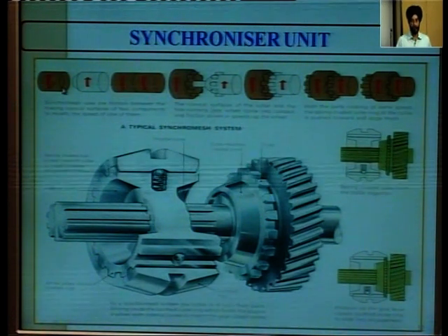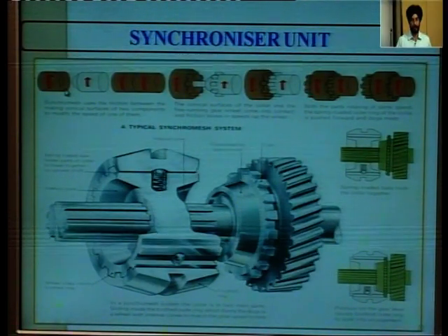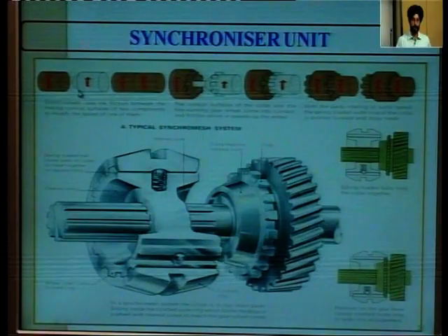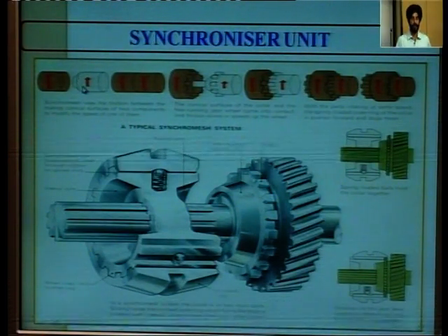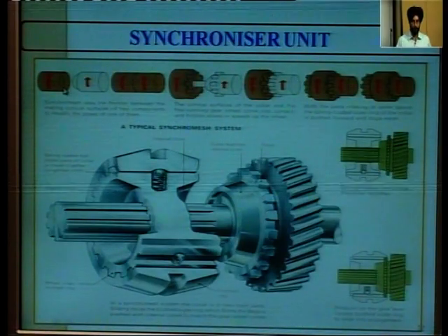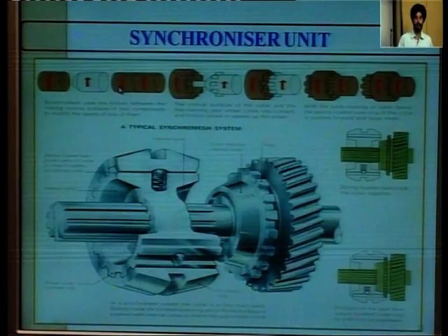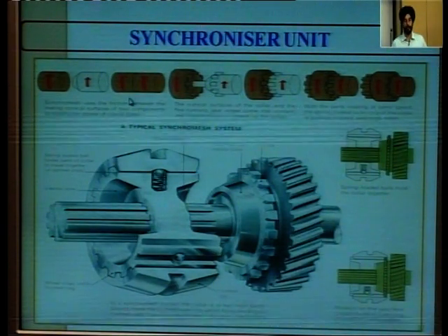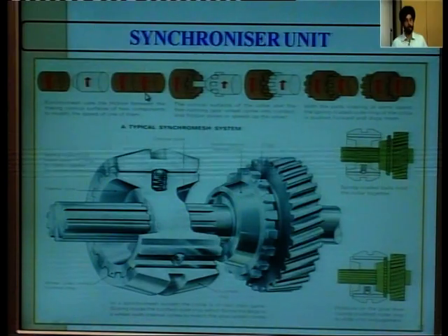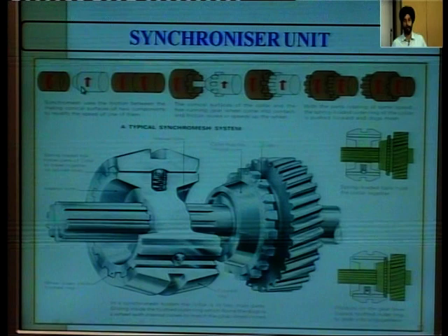Say we have this shaft which has a conical surface inside, and another shaft which has a conical frictional surface. When both these shafts are in mesh, as in the case of 2, we can increase the speed of the first, and the increase of speed will be transferred to the second shaft through friction of the conical surface.